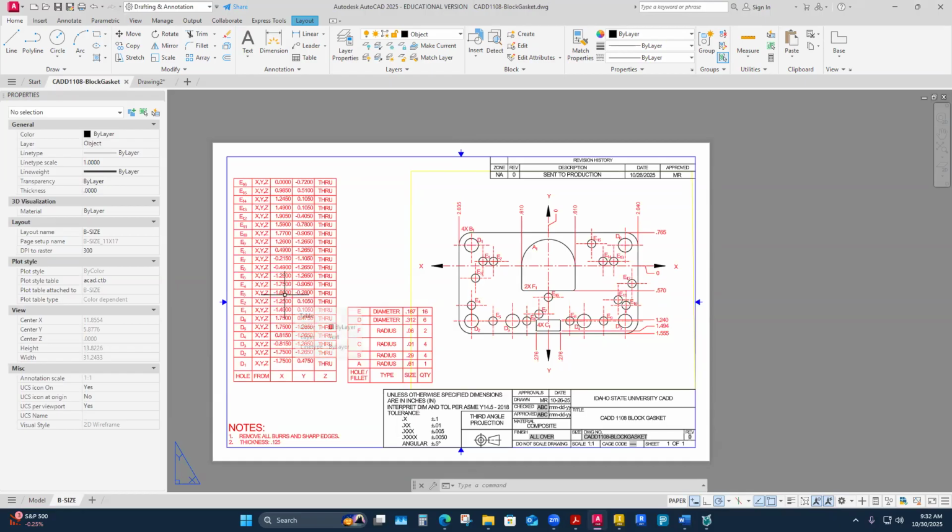It doesn't really say in our instructions to carry those to 4 decimal places, so I just use the default. AutoCAD is drawing to 4 decimal places. That's why these coordinates have 4 decimal places. When it comes to the actual sizing, I'm using whatever was called out on the drawing, I think. I'd have to check this because it's funny, I'm thinking I'm missing something. I don't see that 0.005 radius listed.